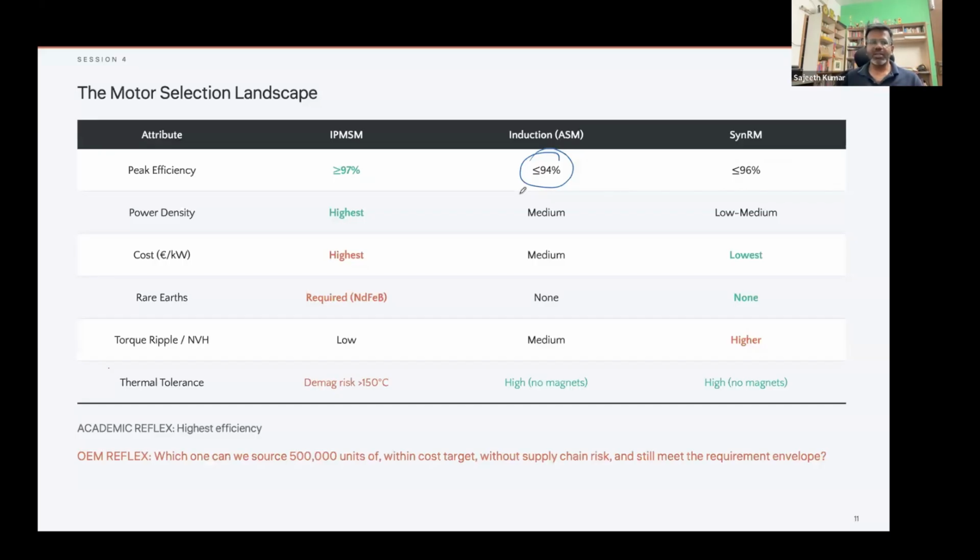But I would be very surprised if you find the same happening with, let's say, an Ather or a Suzuki EV or a Toyota EV or a Hyundai EV for that matter. You would probably not find this happening a lot, right? There will, of course, be a one-off incident which happens even with these, but to a large extent, this is basically controlled by very careful battery pack design, by implementing cooling into the system. In fact, for the EV two-wheeler that we are designing, we have both passive and active cooling systems. We are running it in Indonesia. Indonesia would probably be even hotter. So yes, we do need to take some considerations for it, which is thermal considerations.